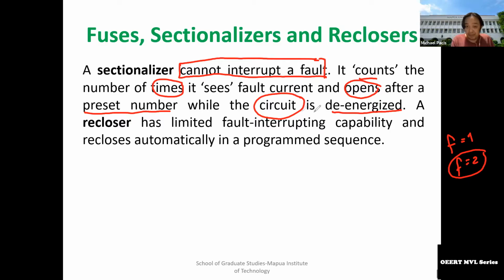So meaning, ang de-energization will be done by a recloser. So bibilangin ng sectionalizer kung ilang beses nag-reclose o how many times the recloser recloses. So it depends on frequency. If that is 1 time, 2 times, but if you set it 2 times, then the sectionalizer will definitely open to interrupt the faulted line.